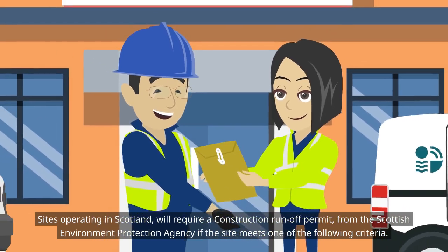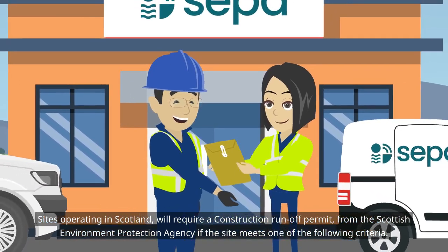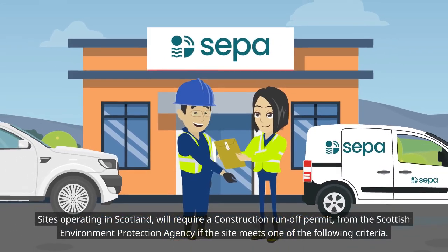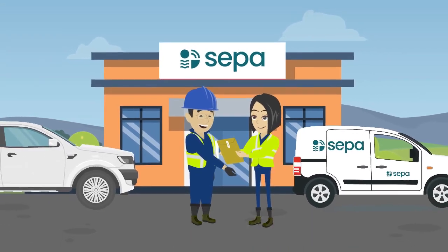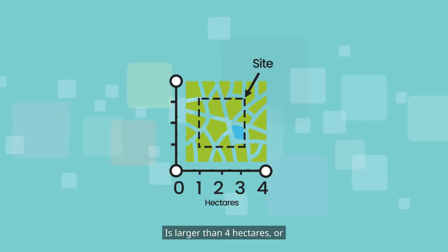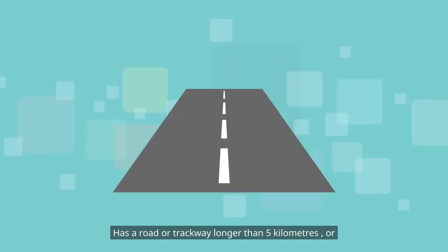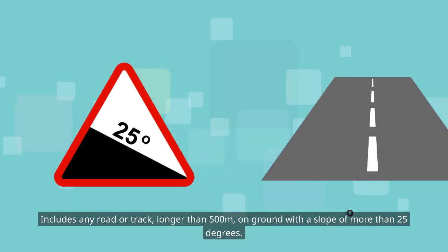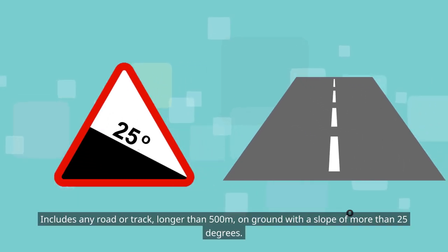Sites operating in Scotland will require a construction runoff permit from the Scottish Environment Protection Agency if the site meets one of the following criteria: is larger than 4 hectares, or has a road or trackway longer than 5 kilometers, or includes any area of more than 1 hectare on ground with a slope of more than 25 degrees, or includes any road or track longer than 500 meters on ground with a slope of more than 25 degrees.